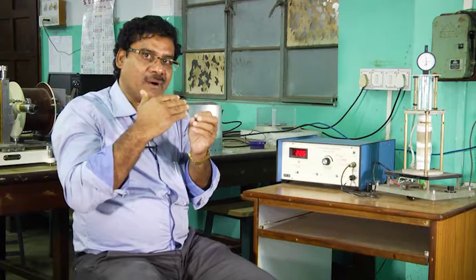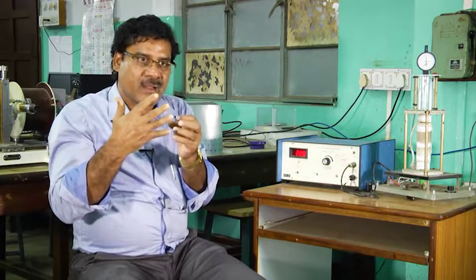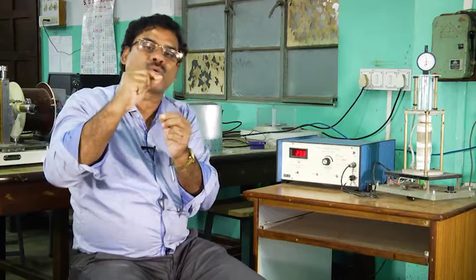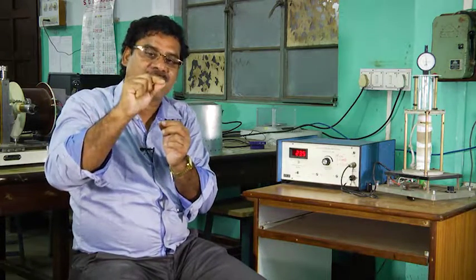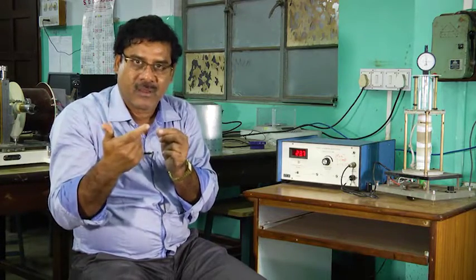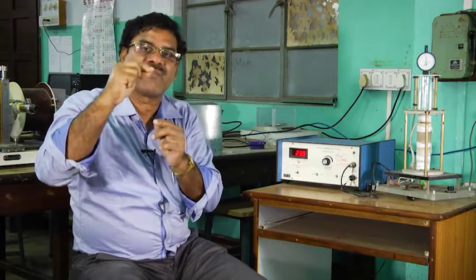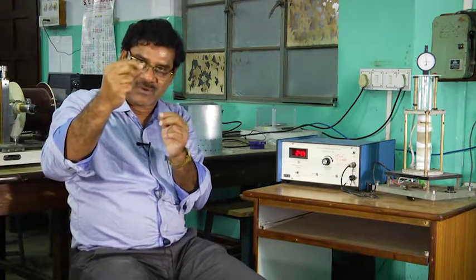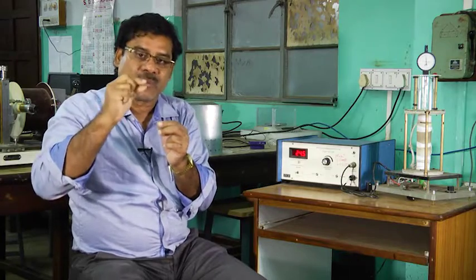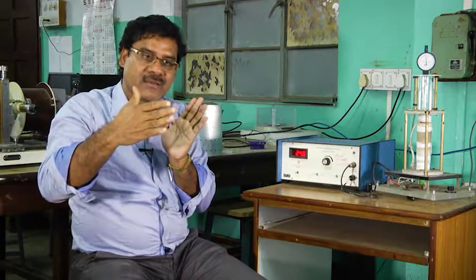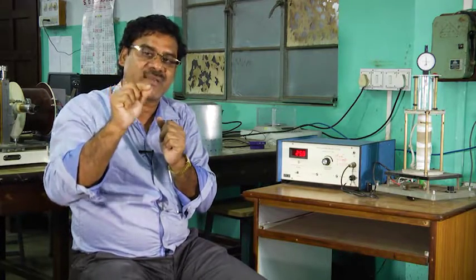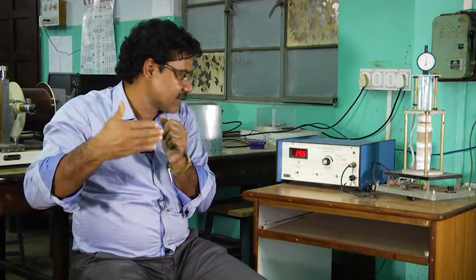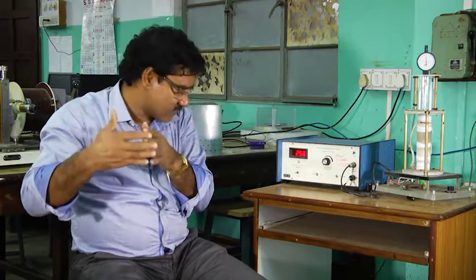So, power is given to the oven proportionally. Okay. And then when it goes close to 150 degrees, it cannot just suddenly go to 150 and stop. So, what it will do is go beyond 150, say 155, then it will say no, this temperature is higher now, so it will come back. So, here basically integration and proportional. Because it is a slight change, not this high gap. Now, from 150 that change is within plus minus 5 degrees. Okay. So, then it basically does the integration, this feedback, and its power is given through the integration circuit.